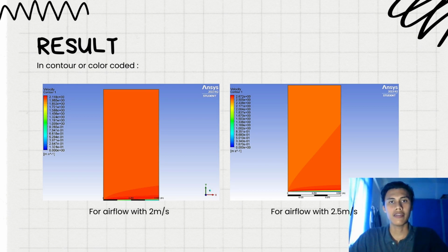If we look at the range of velocities, it goes from 0 to a little over 2. Despite almost uniform velocity coming in, the boundaries quickly get formed and it grows slowly. Here we can see the thickness of the boundary layer is much smaller than the length of the plate.